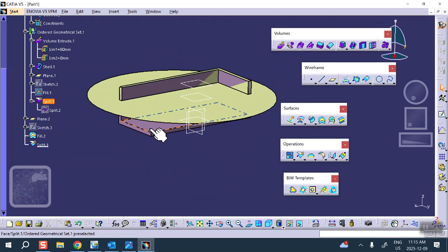The moral of the story is that if you use this with a surface that's outside of that geometrical set, it won't cut the volume for you, but it creates the surfaces that somehow are related to that volume. You've got to be very careful when you use this because you may not get what you're looking for.